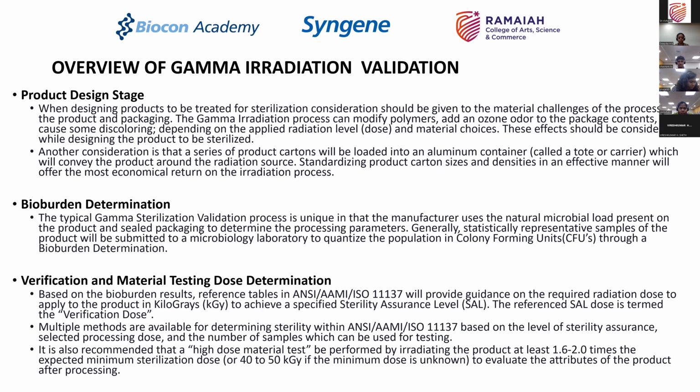The gamma irradiation process can sometimes modify the polymers, though it's non-reactive. It can add an ozone odor. It can sometimes decolor the product, or it can also modify the polymer slightly, because what you are doing is bombarding it with radiation or with energy. When you impart energy to any polymer, obviously there could be some degradation of the polymer if the radiation level is sufficiently large to cause that kind of decay of the material itself.